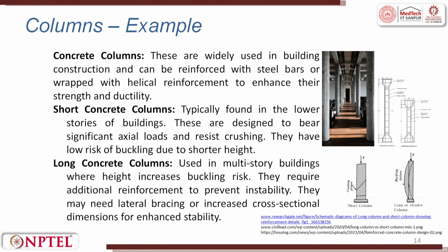Some of the examples of columns: concrete columns. They are widely used in buildings construction and can be reinforced with steel bars or wrapped with helical reinforcement to enhance their strength and ductility. Today, what we are doing is we are also trying to have columns wherein we wrap with composite tapes